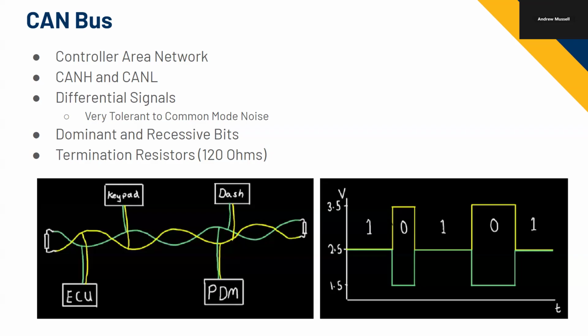Yeah. Like, let's say the ECU transmits the signal. Do all the other ones also get the signal, or do they have to say which one should get it? Yeah, so everything on the bus can sense these lines, but on the CAN transceivers and the microcontrollers for each of these nodes, you can set CAN message filters. So that's something you can do on the CS side. You can say, this node should only subscribe to messages with these IDs. So if it sees something else, it won't waste its time processing that data if it doesn't need that information.